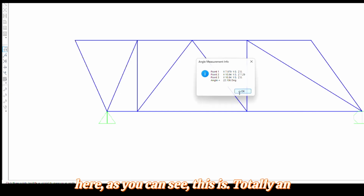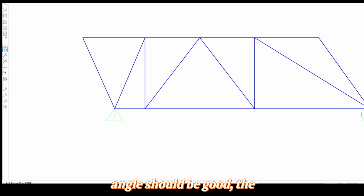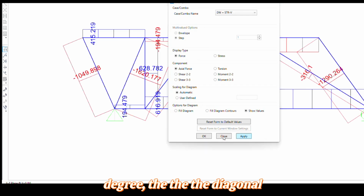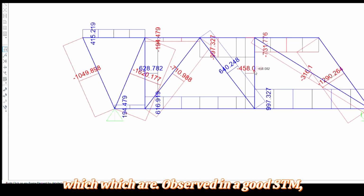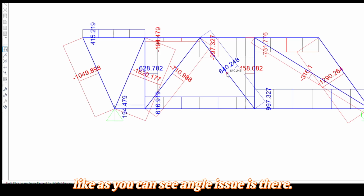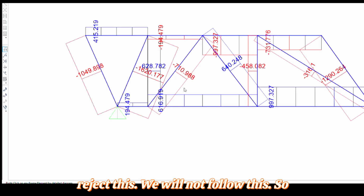So as you can see, this is totally an inefficient model, which one might make, and which I also made when I was doing it, because we don't know what the output would be. So these are the things we keep in mind: the angle should be greater than 25 degrees, the diagonal members should show compression only, and the vertical members should show tension only. These are the things observed in a good STM. But here, angle issues are there and the forces are mismatching. So this is an example of a poor STM, an inefficient model. We will reject this, we will not follow this.